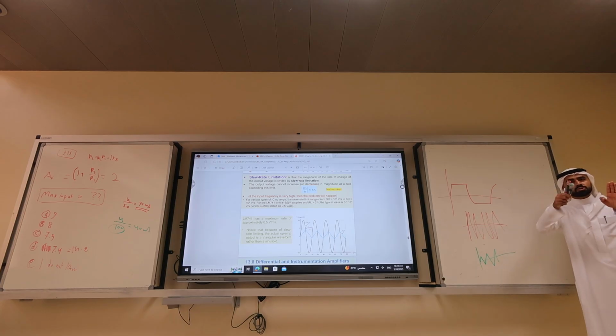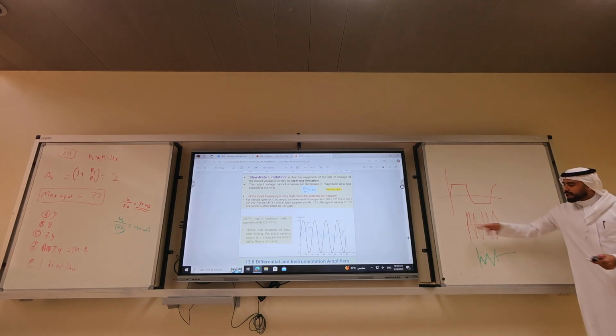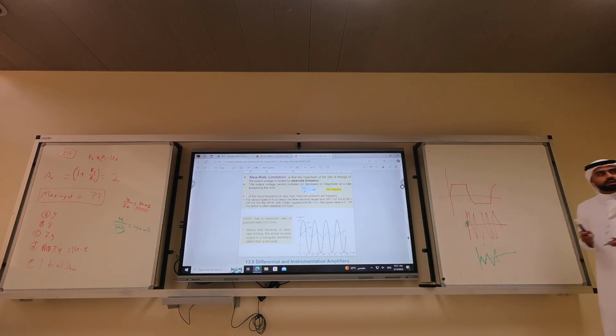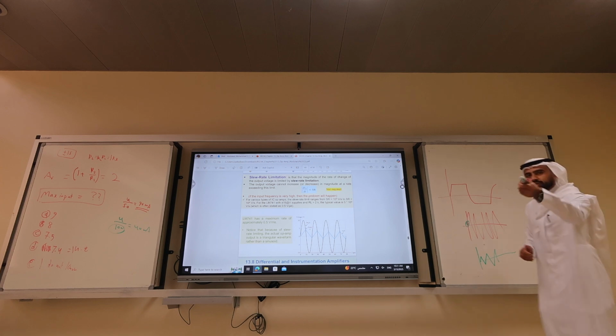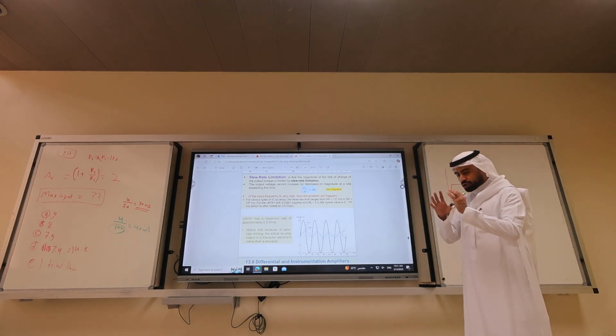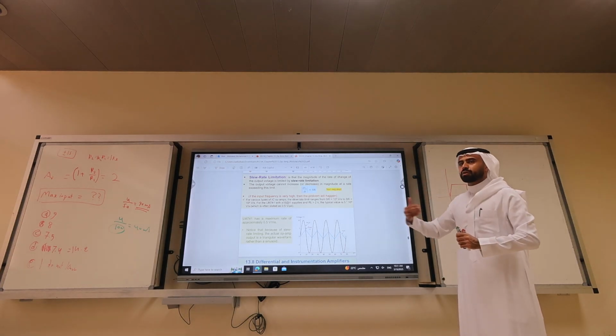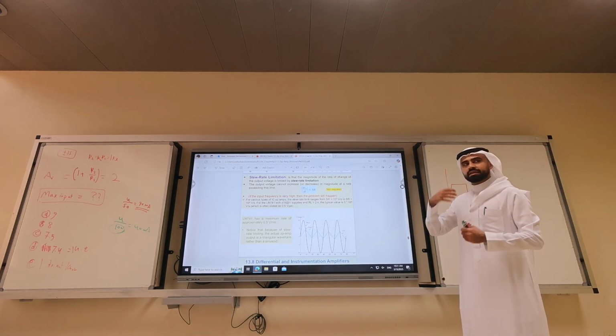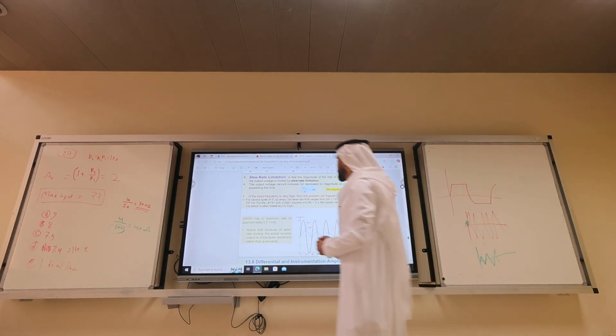Because the input signal is too fast, you only capture this part of the sinusoidal to be amplified. Then we will have a distortion, a non-linear distortion. Get it, Turkey? Yes. If you have a very high frequency signal with cheap op-amps, you cannot hear that frequency at the output. Okay? Because it needs some time to catch up with the signal.